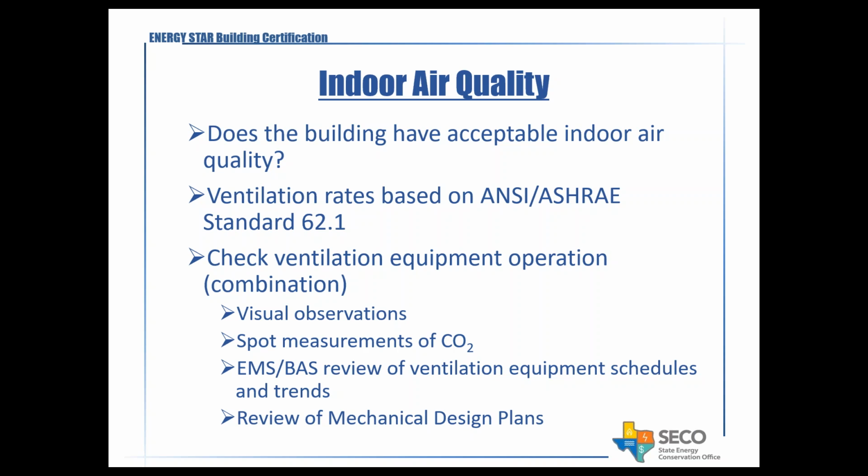In other words, this is not a test and balance kind of on-site visit in which we are measuring the amount of outside air on each of your outside air intakes. Mostly we'll be looking at whether dampers are open, looking at the EMS to see if the dampers are open and modulating, and then looking at the original design plans to make sure that it meets the current IAQ standard.